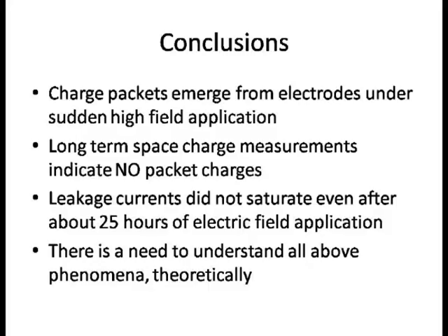So whether the space charge will actually cause a problem in the long term is not an easy question. The investigations are still going on, so right now I don't want to make a final conclusion. Leakage currents also did not saturate even after 25 hours. Now we are planning for more than that. We want to conduct experiments for several days and then see the results.